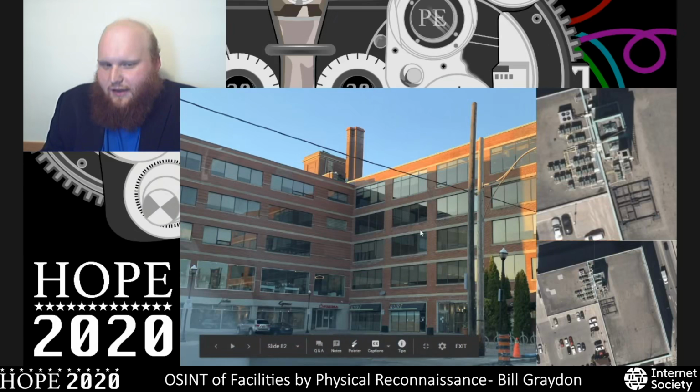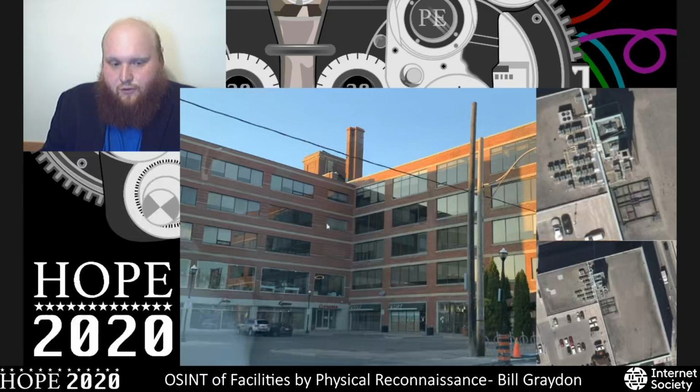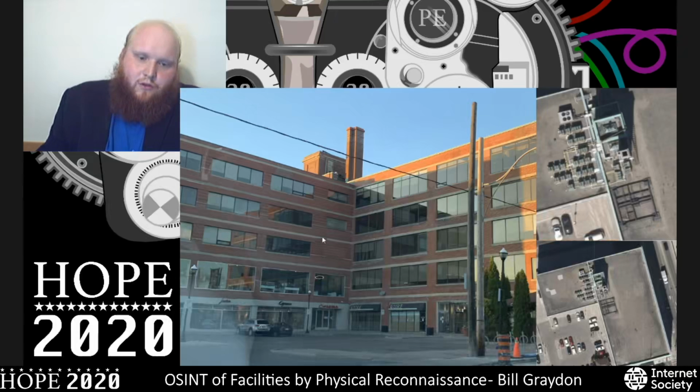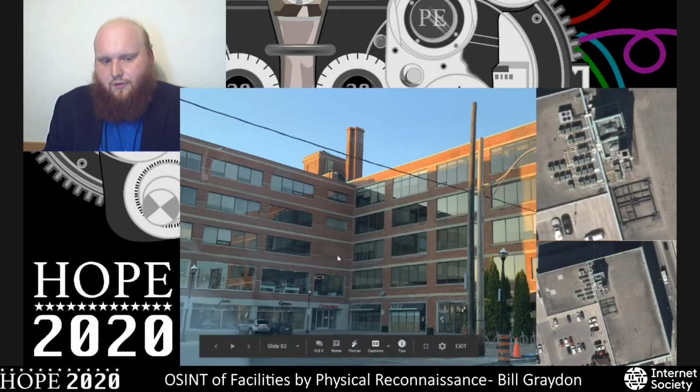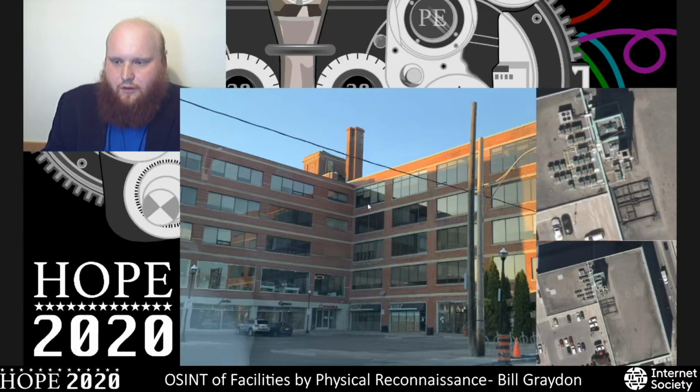In buildings like this, you tend not to see complete basements, but we also notice this break in the windows here. So this is likely where the boiler room is. It's interesting to note that it's 2 stories because most boilers are taller than the average floor. So if they're interstitial in the building, they'll likely be 2 stories spanning. If they're in a penthouse, that's part of the reason why mechanical penthouses are taller than most occupiable floors. And if they're in a basement, they're likely downstairs from the regular basement level.